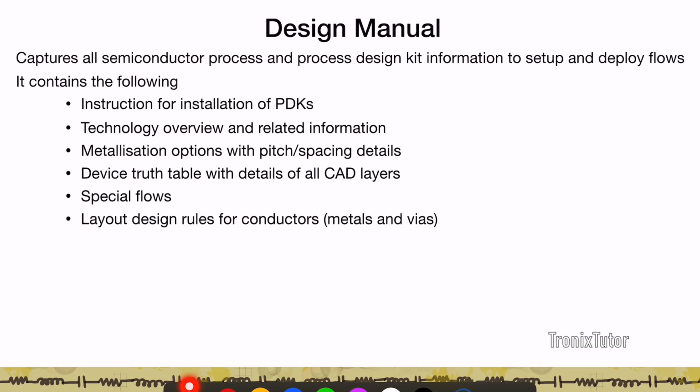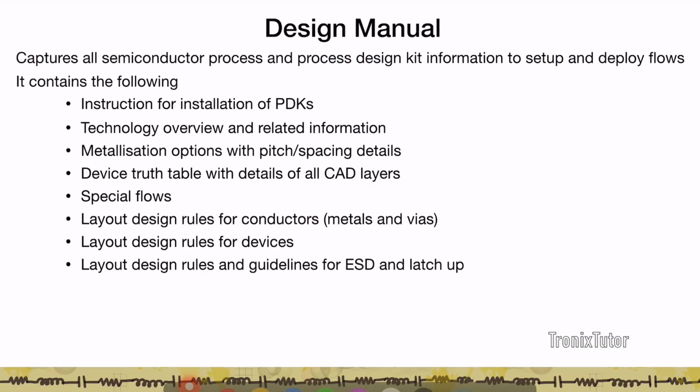Layout design rules are important. As I said, this is critical to designing a mask that is able to give you yield-worthy silicon. So this gives you the kind of design rules that you need to follow. Similarly, you have a bunch of rules required to create devices, and that would be part of the design manual. Specific structures like ESD and Latch-Up would require additional rules, and those will also be part of the design manual. Reliability, right? What happens as transistors age, as metal lines age, is also released in the PDK, and specific rules are available if you need to meet specific targets.